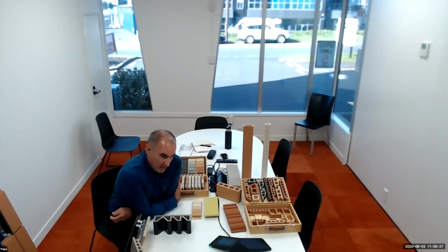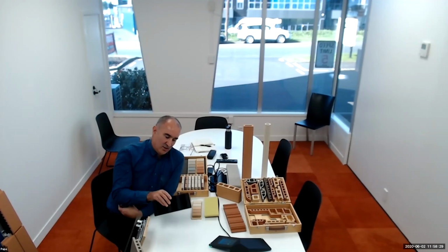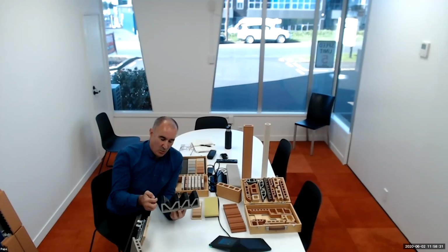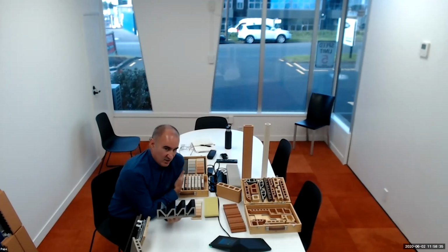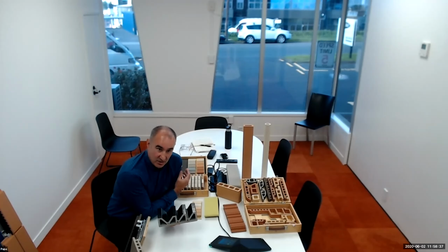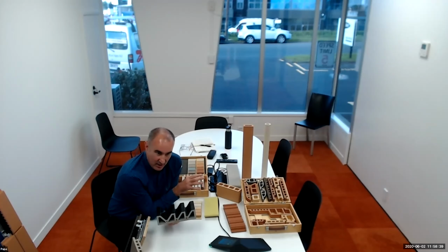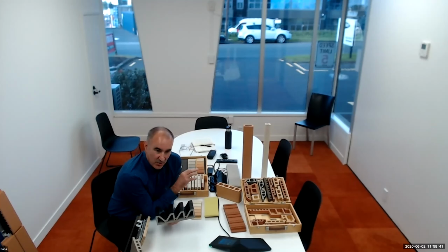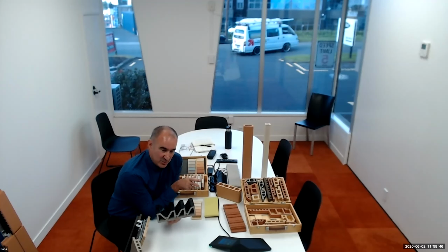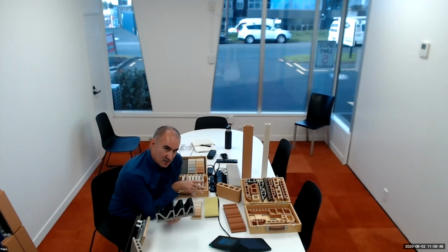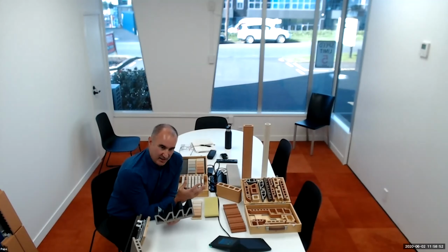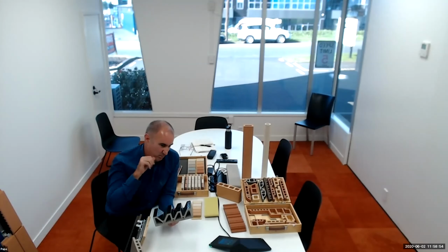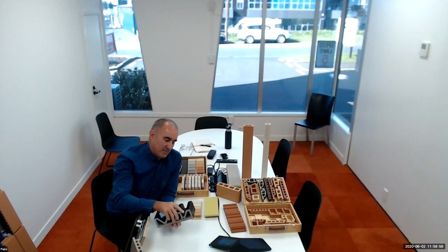A die is made, and what I mean by a die is it creates the shape that you want it to come out to. The size of that die depends again on the colour, because clays shrink at different rates. So you may need different dies to create exactly the same size tile in different colours. But again, we can take care of all of that for you. It just gets extruded out, pushed out through the die.